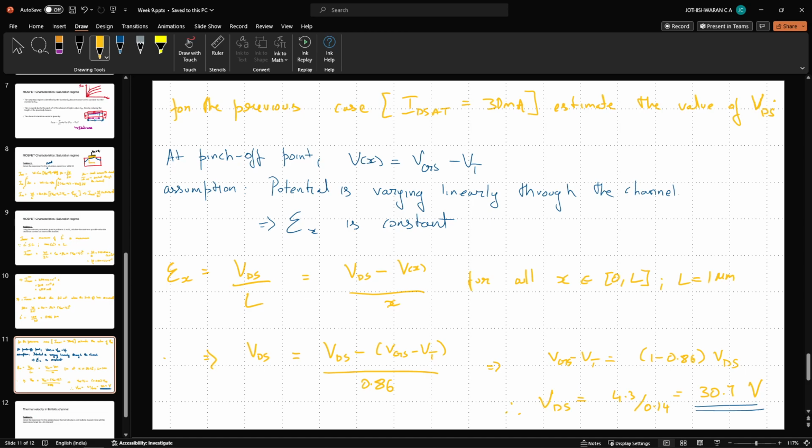I shouldn't say classical MOSFET, because even to observe basic transistor effects, we have to reconcile with the quantum nature of matter. We cannot derive transistor behavior through purely classical means, because even p-type and n-type materials cannot be defined without quantum mechanics. What I would say is a bulk MOSFET, a macroscopic, long channel bulk MOSFET, shows this kind of behavior. Now, this is the pointer that we need.